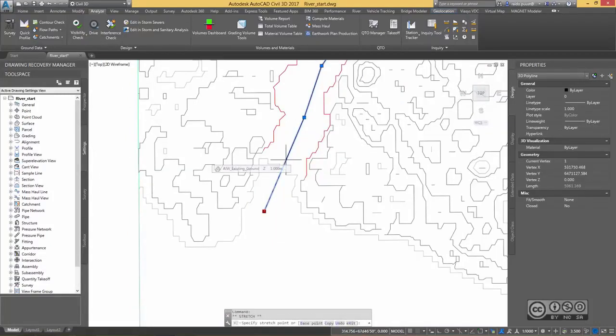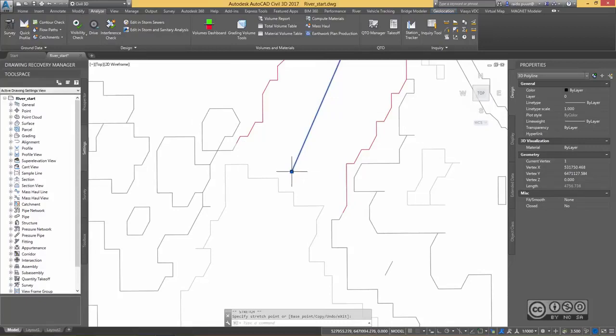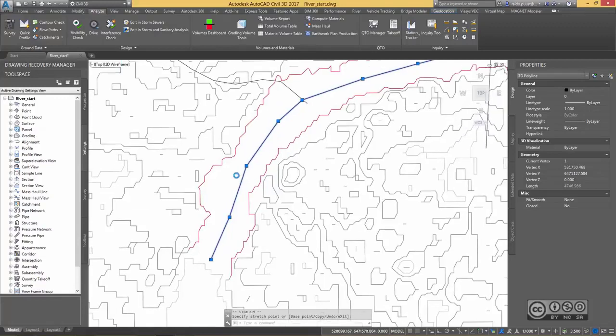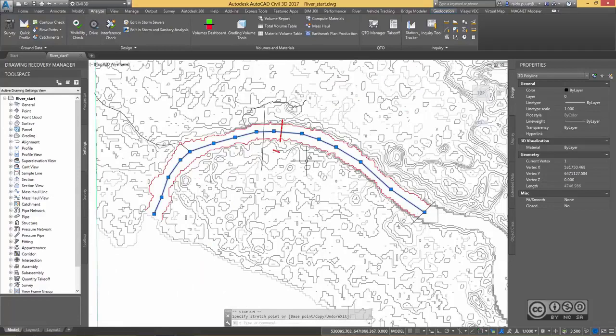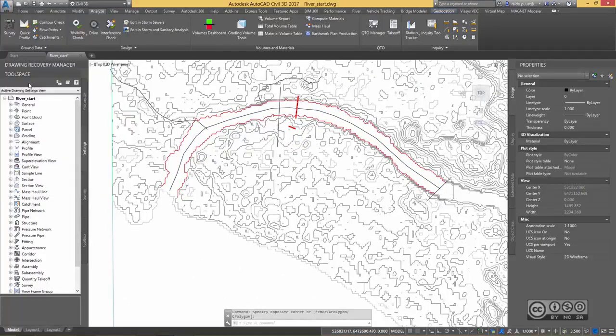changes close to shoreline. I want to ensure that my line endings are at about the same level, because we are creating cross sections based on the 90-degree rule. We can imagine approximately to where this line should be placed, but those small changes can be made later on if we find out that something doesn't work out. Okay, this is now modified quite well, so we can move on, and I will save my drawing.